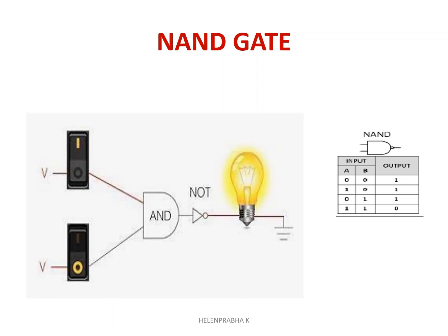So you can use this NAND gate for any quiz, or you can use it as a buzzer, right? So if both the persons press, let us consider this AND with the NOT, if both persons press high, then the buzzer or light will not glow. If any one person presses the button, then your light or alarm, buzzer will glow. So that way you can use this NAND gate for your application.